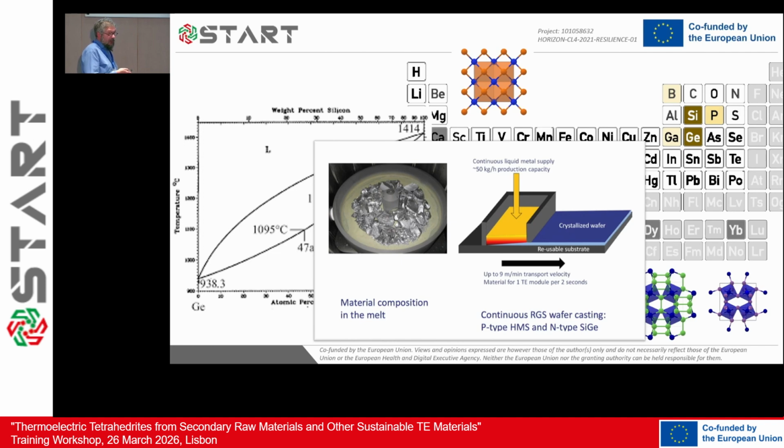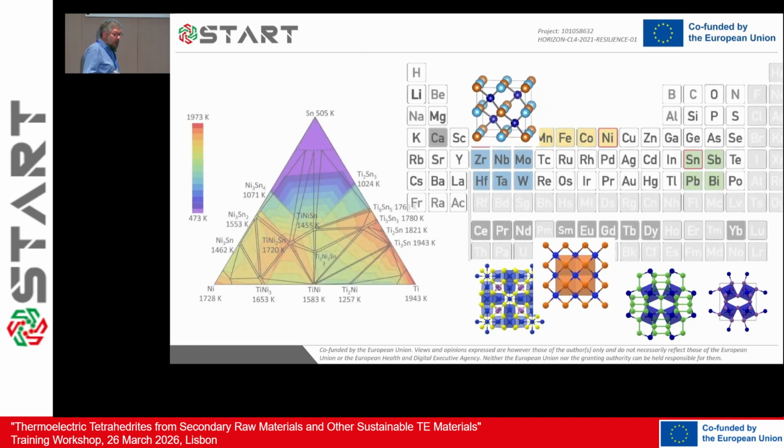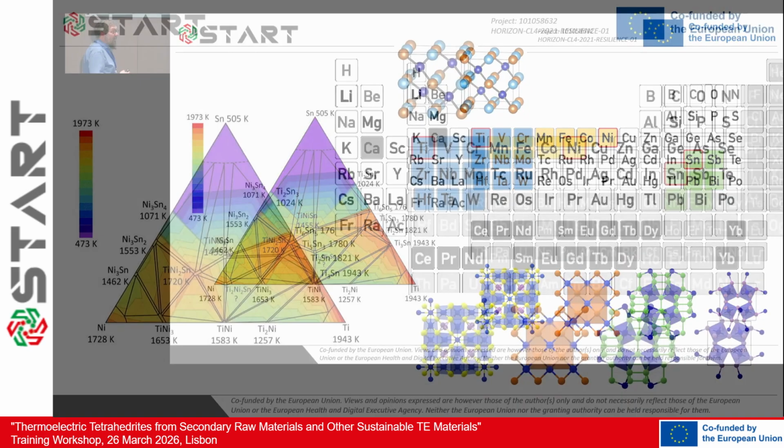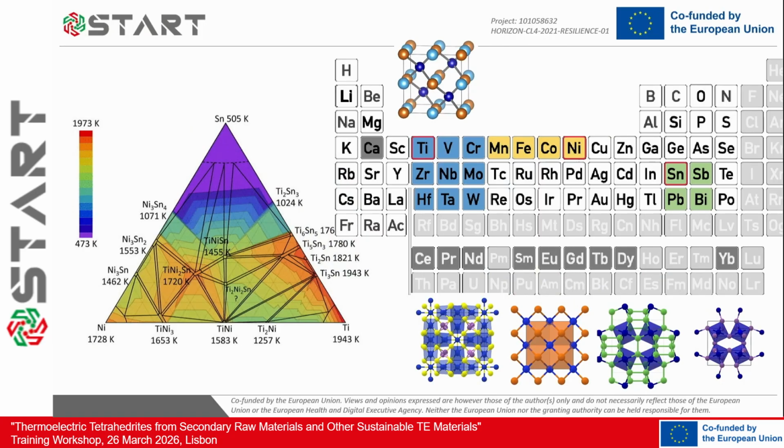And we are still talking about basically two elements with their dopants. If you are talking about more elements, things are even more complicated. If you're lucky, you can get it quite quickly, but the number of different phases that can be formed using the approach of melting everything down and cooling is basically exponentially increasing, especially if you want to add other dopants and substitutional elements to increase the properties of the thermoelectric material.